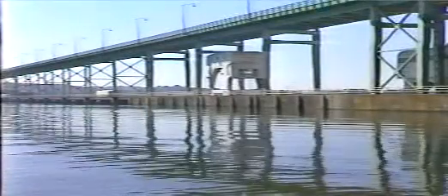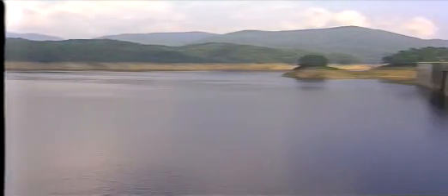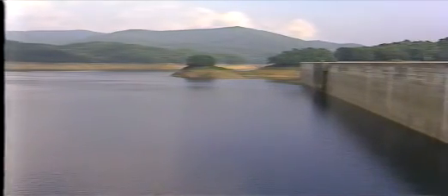Locating deficiencies on the upstream face may be difficult. You are usually limited to looking for deficiencies above the waterline. Make it a point to visually scan the upstream face from the crest, the abutments, or if you have the chance, from a boat. When or if the reservoir is low, use the opportunity to look for problems on the upstream face that are normally underwater.